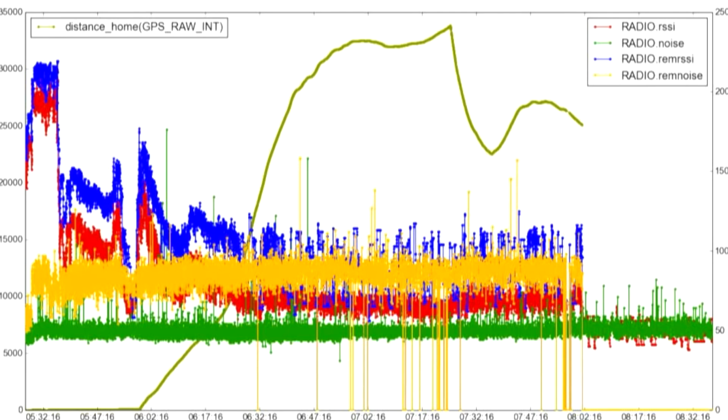And it was great when it was first turned on, but then a few minutes after the whole system was first turned on, suddenly the noise rose quite considerably, from about an RSSI of 60 up to about an RSSI of 85 or 90. So a difference between 60 and 85, that's 25 RSSI, which is about 12 dB. So we suddenly got 12 dB more noise from something else in the payload, because this wasn't an exclusive payload. So there was some other radio transmitter.